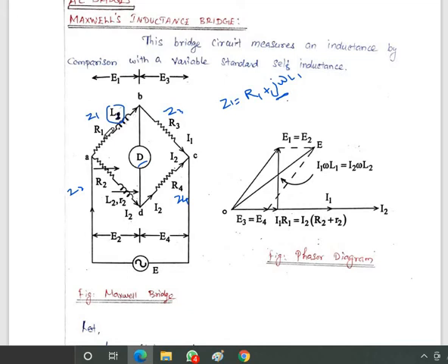That means XL can be found by omega L. Omega L is the inductive reactance, XL equal to 2 pi FL. 2 pi FL is the general formula, the inductive reactance. So it can be represented as an imaginary one. That means it will oppose the actual input voltage, so some voltage will be opposed. So it is represented as an imaginary part.